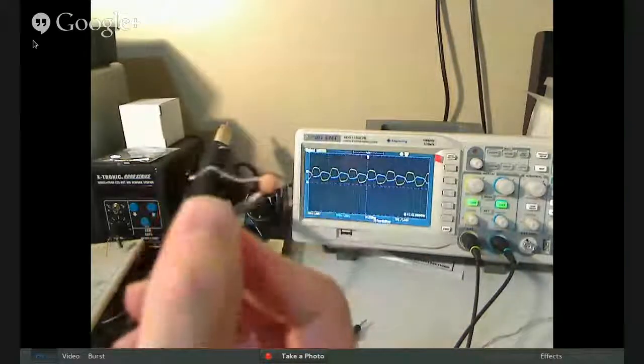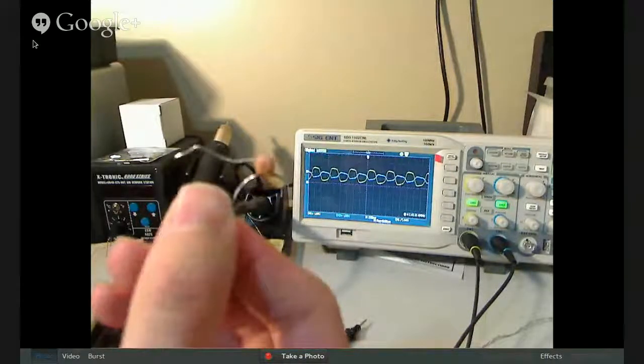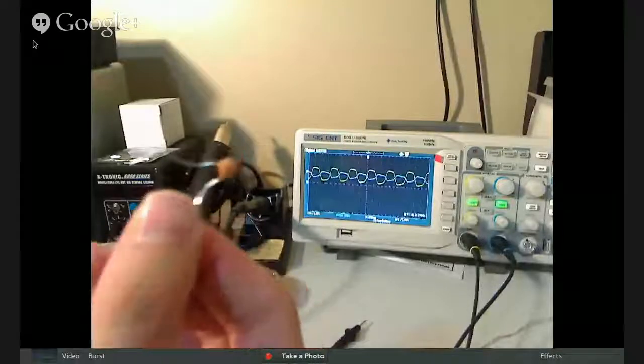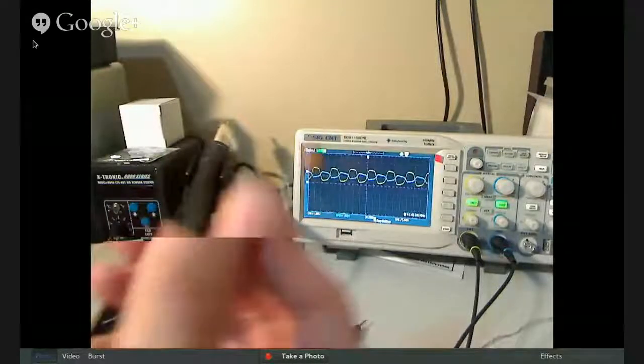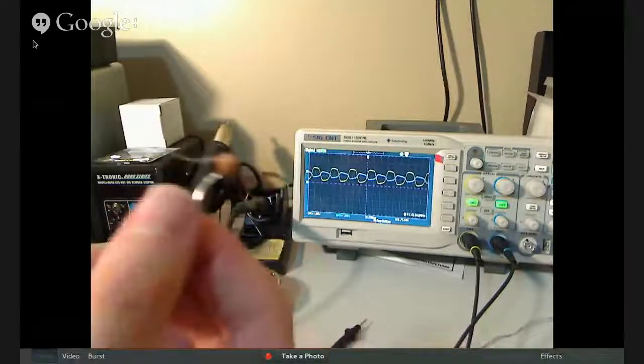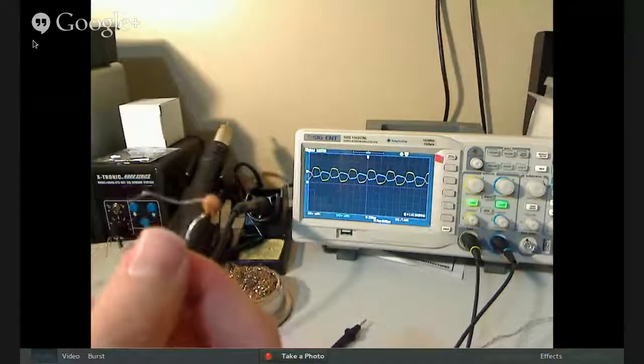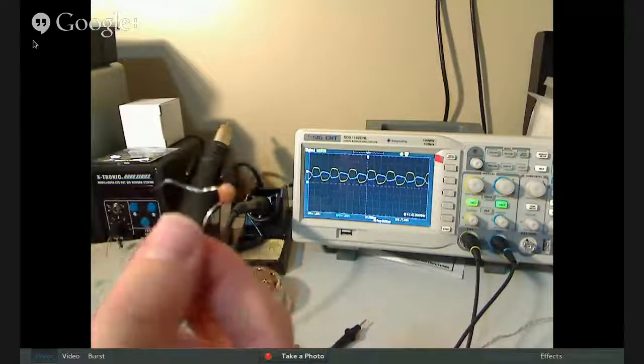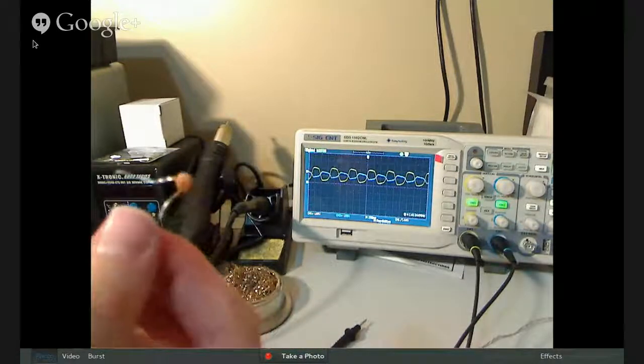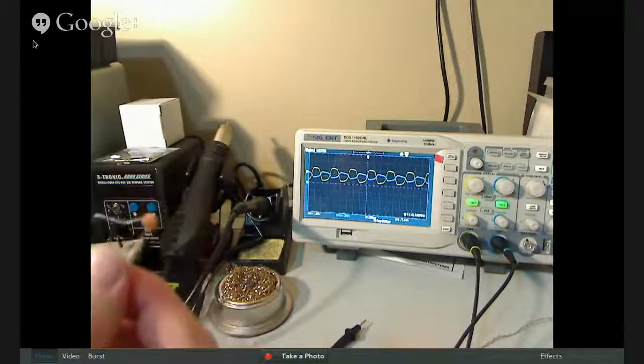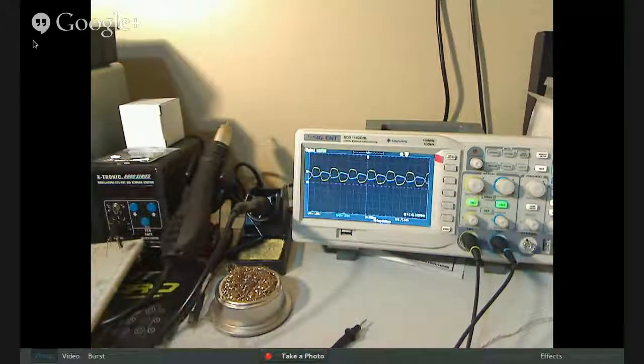It's a ceramic capacitor. A capacitor is basically just a way to store an electric field, an electric charge. It's like a very small battery with very little capacity, at least this one, that can charge and discharge very rapidly. So I'm going to put this in. I'm going to put it between the base, on the other side of the resistor, and ground.